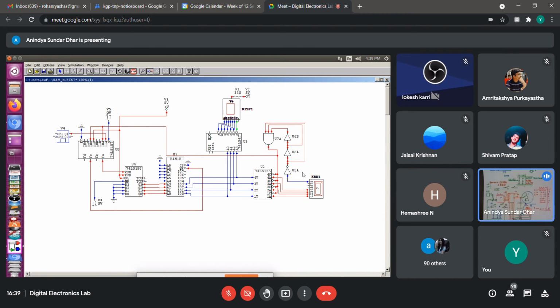Question mark makes all the lines from this hex keypad high. Okay, so let us see if I press question mark. What is the use of pressing all high? What will be displayed? Blank. If I send all 1 into the 7447, what will be the display? Blank.